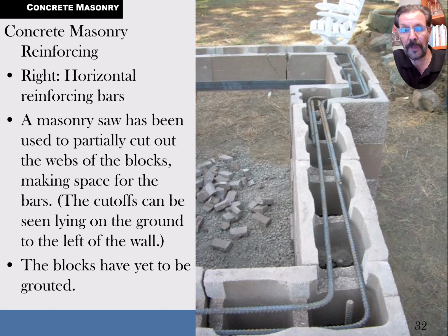What's more common in big commercial jobs anyways, is to buy special blocks that are already U-shaped, that are, when you're looking down the barrel of the block, you're looking at a U. And so you have this hidden path that's much deeper, maybe 6.5 inches, that they can make a 6.5-inch deep beam through, and then they'll chair the steel up in it and that sort of thing. Okay, so that's a bond beam.